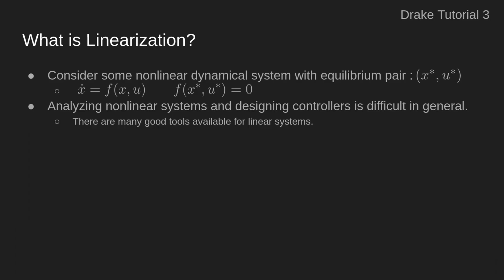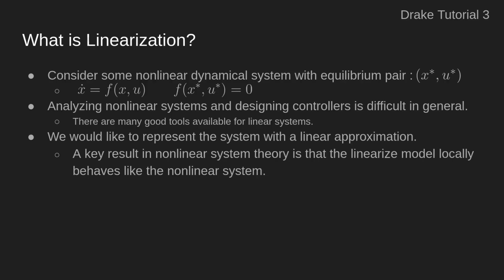In general, analyzing nonlinear systems and designing nonlinear controllers can be challenging. The tools used in nonlinear control theory are by nature more complicated than that for linear systems. What we'd like to do is apply linear control techniques to our nonlinear system. Thankfully, we have a fundamental result from nonlinear system theory, which states that nonlinear systems behave like linear systems locally.